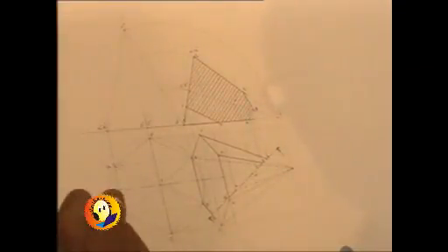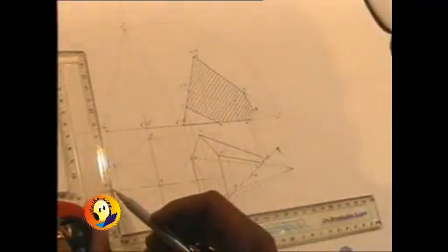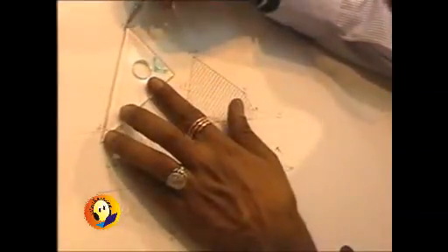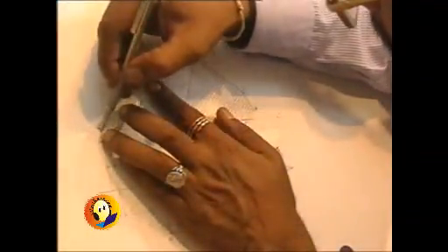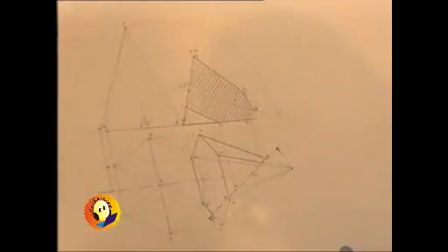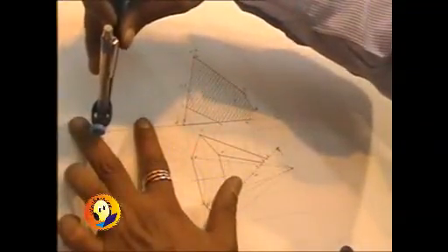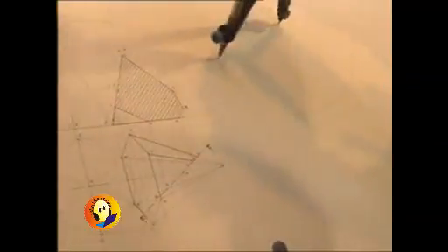So in this case I will be rotating say AV and making it parallel to XY in plan. So the circle was already there, so my job is slightly simpler. And then that point should be taken up, and then it should be connected to the vertex to get the true length of that generator. I am drawing it middle dark because it is a construction which will be very useful also. And so take that distance in the compass, the true length, and then using that true length draw one arc where the development is to be drawn.